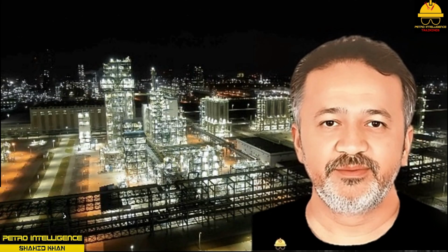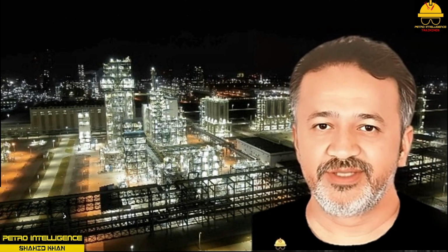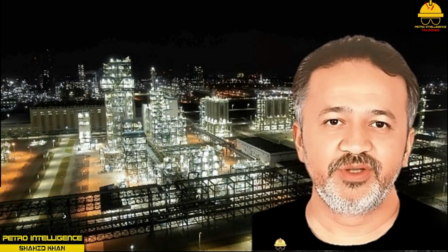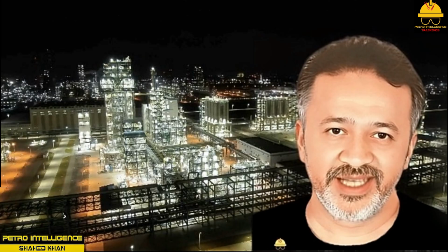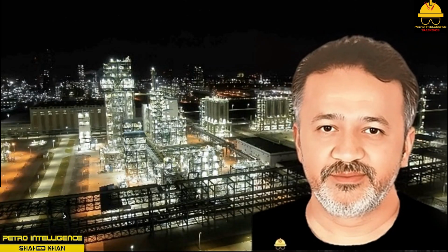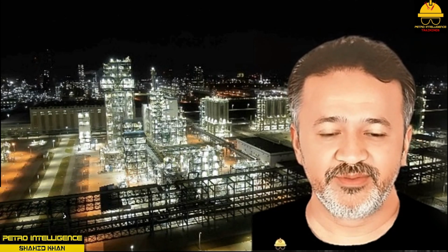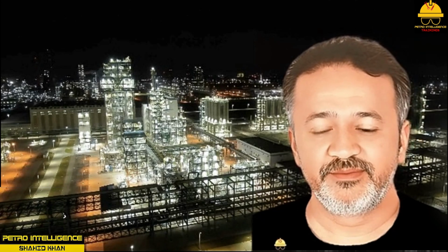Analytical control loop. An analytical control loop is typically designed to use flow to control some compositional variable. For example, the pH of a cooling water basin may be controlled by adding acid or caustic. When the ppm in the water basin exceeds operational guidelines, the analytical control loop removes a specified percentage of the basin water and replaces it with fresh water. Analytical control loops can be applied to a wide assortment of operational processes. This picture shows an example of a series of compositional control loops.